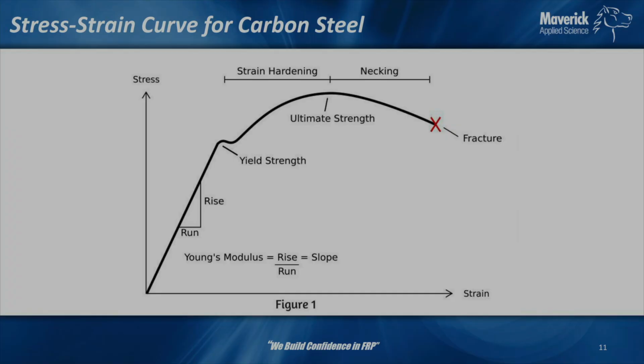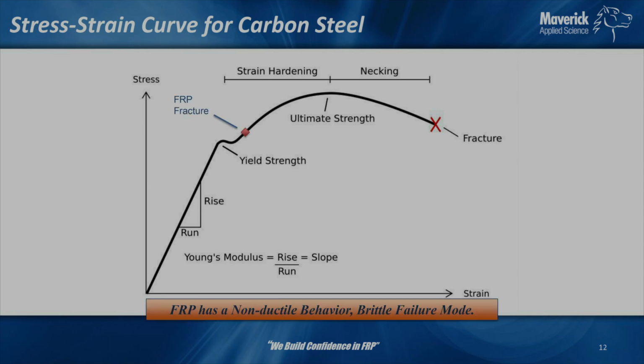This is something I haven't put out, but I thought we talk about it a lot, and this really tells a story, especially if you have an engineering background. So this is our typical stress-strain curve for carbon steel. We have our basically elastic range here. We go through a yield point, and then it's going to basically start to deform more until it finally fails. This is what we know carbon steel to do. Usually that plastic deformation, where we have thinning and stretching, is about 20% or something in that order for carbon steel.